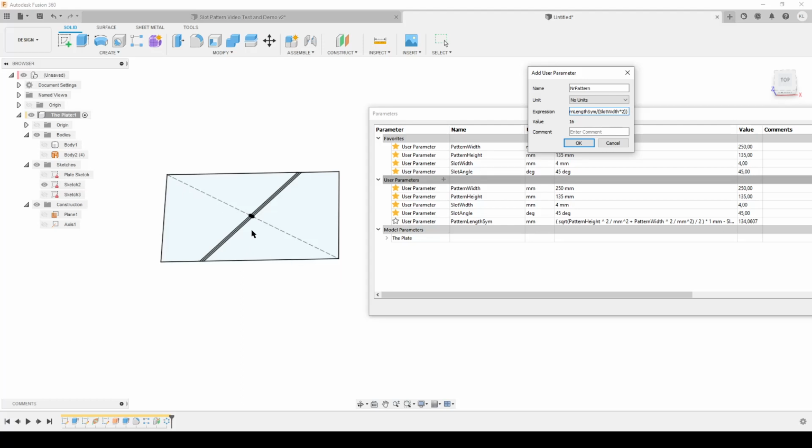And let's see now, the problem with this is of course that this pattern is including the one in the middle here, because when you do a pattern it includes the one you start with. So you could do minus 1. And let's see, am I thinking correctly here? Yeah, I think so. So this is of course the number of patterns on one side, and when we do the symmetric we need to tell it patterns on both sides.